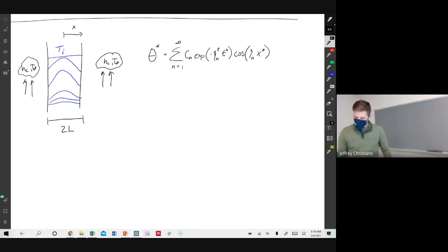We had two weird equations. Well, one weird one and one that's okay. So this is an infinite sum. We had this little C term, little squiggle n. Cn, we found from this recursive formula, Biot number equals Cn tangent Cn. And we said this equation works, but we have to find multiple solutions.